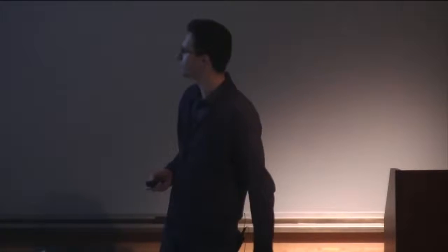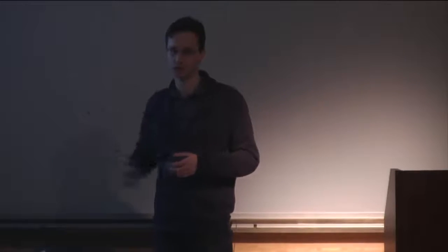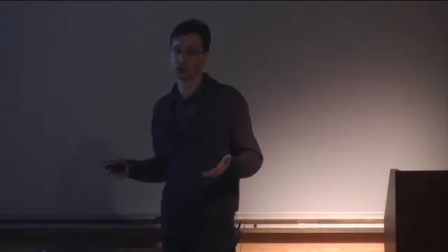Yes? What's the advantage of this method over 1.5 where you're replanning? So the main advantage of this method over 1.5 is that in step 4, you just run your policy. The policy dynamically selects an action in response to the current state. So that means it's going to compensate for mistakes, to the best of its ability, and you don't necessarily need to replan every time step. Presumably, it's not going to be quite as good as replanning every time step, but it potentially is a lot cheaper.